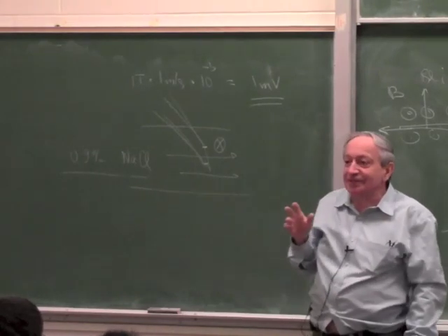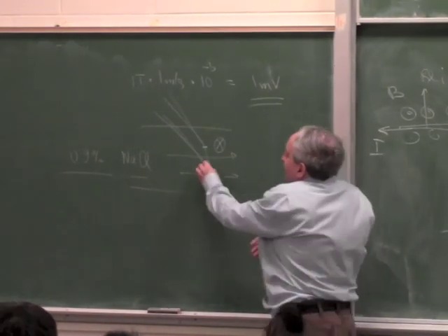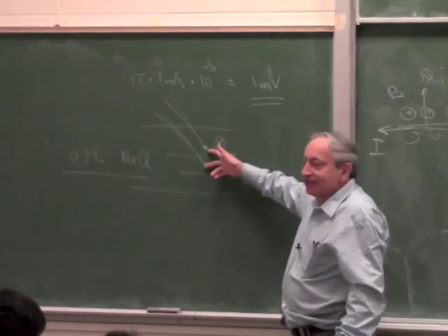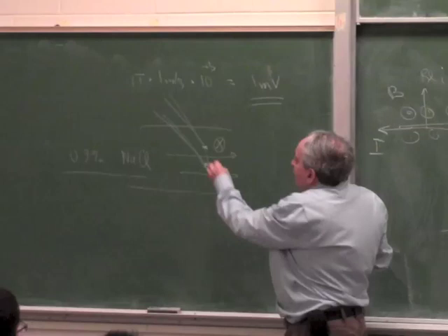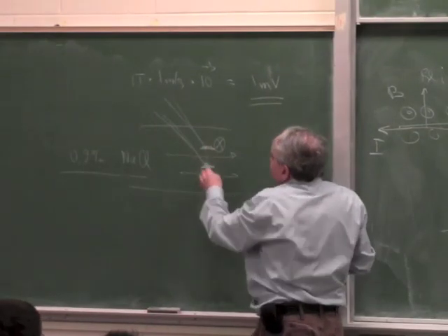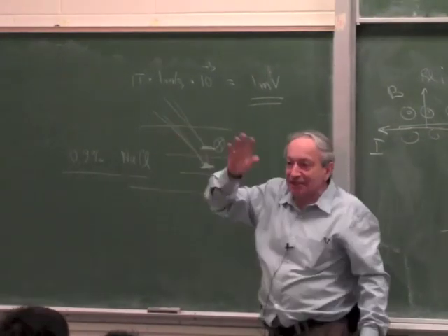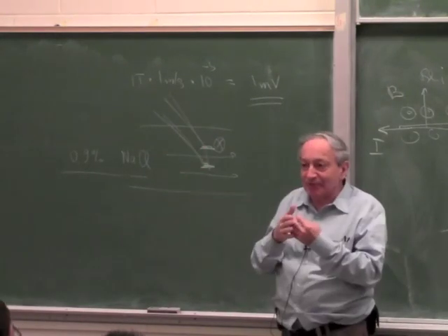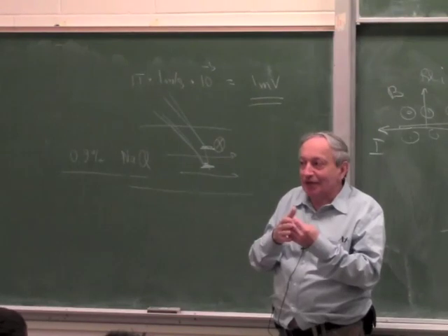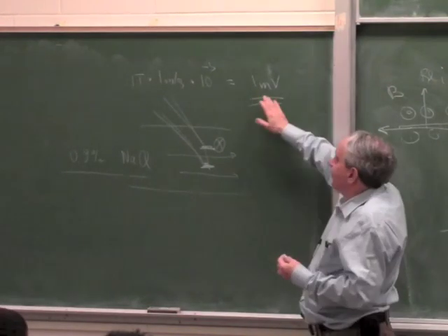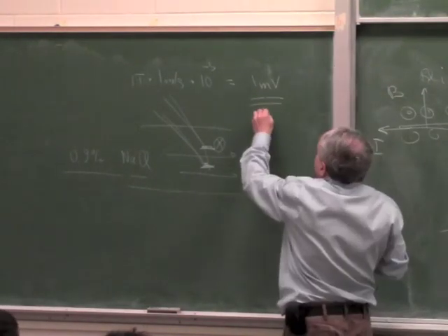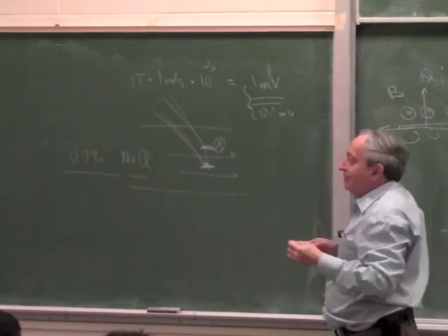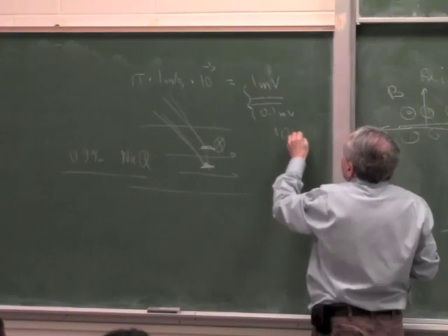Now, of course, there are problems. When you do that, there is also some galvanic effect, because this also forms a battery. Let's say you have 2 wires and the metals are slightly dissimilar and the needle is the third metal, so you also get DC voltages because it forms batteries. If you want to measure this 1 millivolt or 0.1 millivolt to 1% accuracy, you have to go down to 10 microvolt.